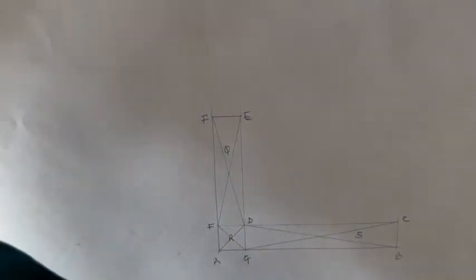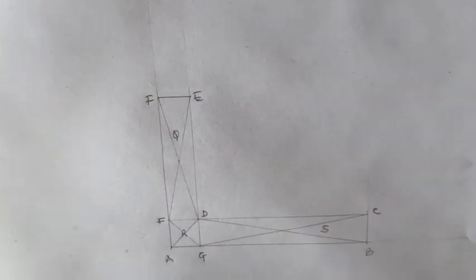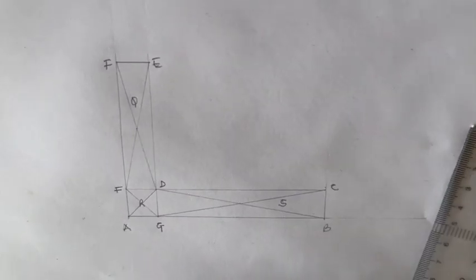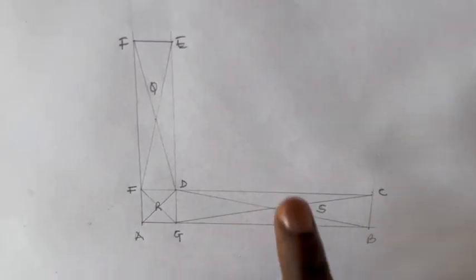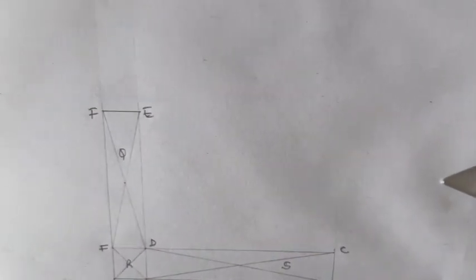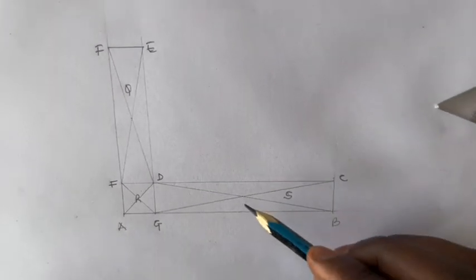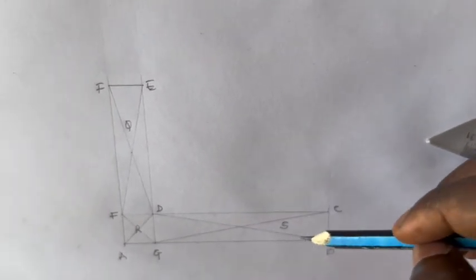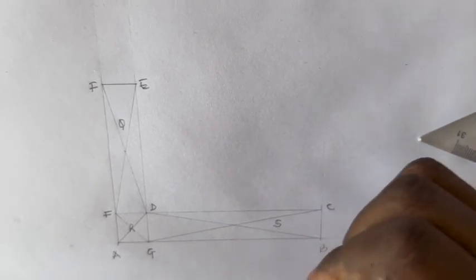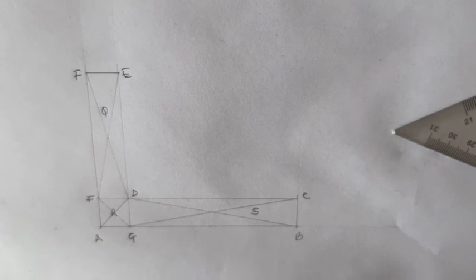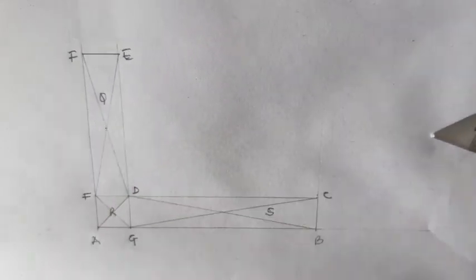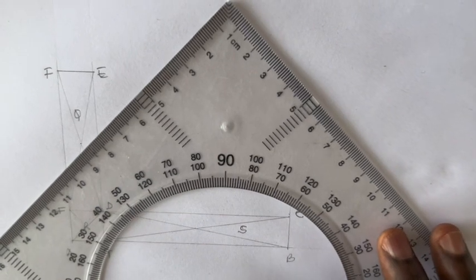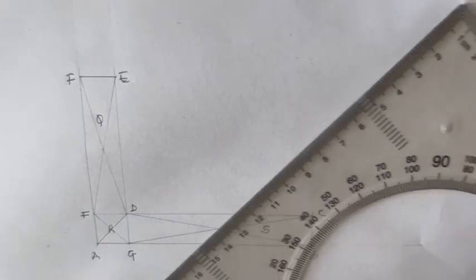Now with that, the next thing that we have to do is that we have to look for lines from the object. So we are back to the main object once again, and we are going to look out for lines. And because of how this particular diagram is, if we should project our lines that we're going to work with on our load lines from the center, if we use horizontal lines, we are going to have two lines passing at the same point. And so it is very good that you use angular lines to do that. And to get an angular line, you can use any of your set squares. So I'm using a 45 degrees set square, so that I'll get my lines at 45 degrees from the center of the object.